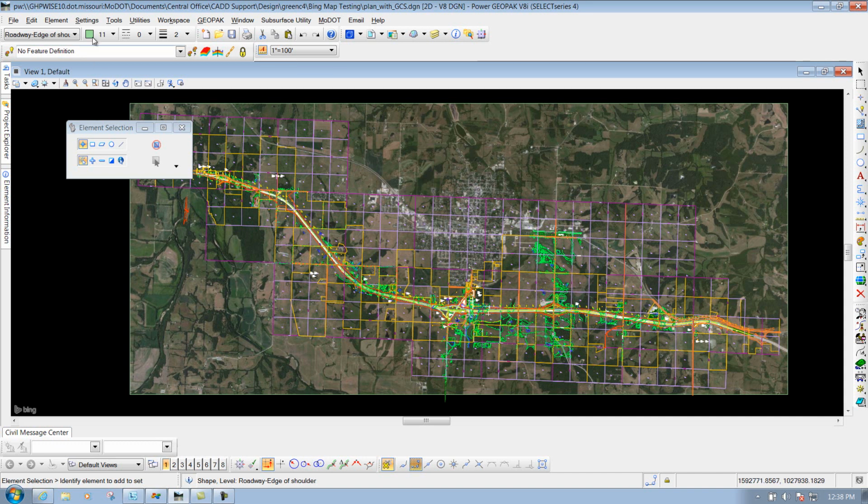To get to print out, we have to use the Descartes plotting. If we use the regular Microstation plotting, it will not print out. It can't. It will not do it. And it all depends on the printer setup and the DPI that we have set up by default on our printers. So we have to go through the Descartes plotting in order to be able to print it out.